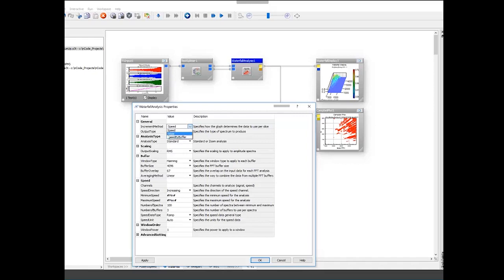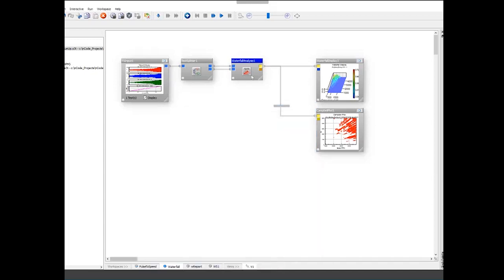So you want to use a speed by buffer. It finds in the speed signal all the sections where the speed is between 3,000 and 3,100, say, extracts all the signals, combines them together, and does the analysis. Basically, it works for both monotonic speed profiles and fluctuating speeds, and that's driven by this property here. So, stop with the theory now.